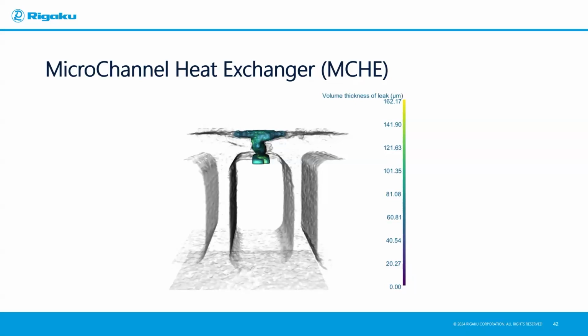And so this is a thickness mesh that's calculated for that small portion, and you can see that it's smaller on the inside, larger on the outside, so you can infer that it's blowing out versus in. And that makes sense since there's pressure with things flowing inside, and that the general length scale for these things is ranging up to, say, 162 microns in thickness. So the thinner things are purple, then as they get thicker, they're green, and then yellow in that case.